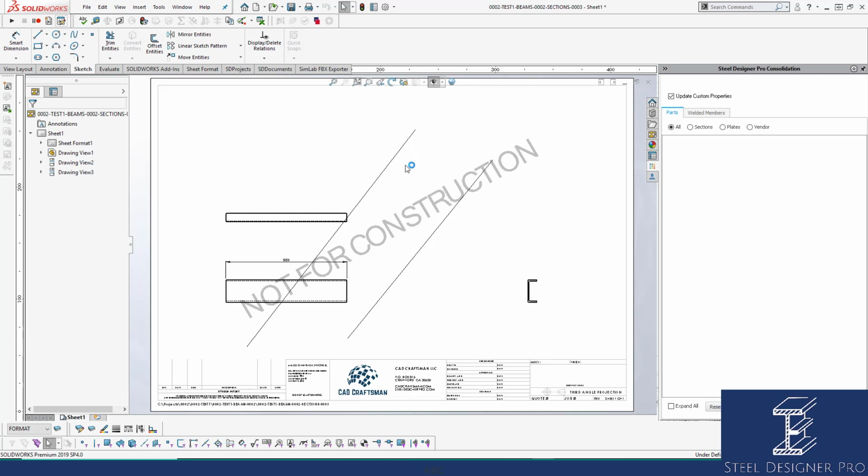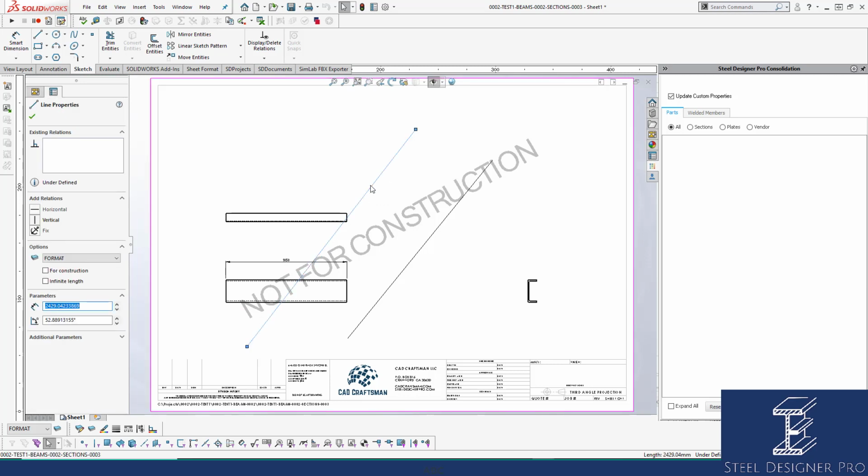So if you've got 500 components that are identical throughout the project, when you go to change a drawing, it will go through each drawing and save the current drawing into those locations and re-reference the component into the drawing. That means that realistically you're treating this like you've only got one drawing, but you may have 500 drawings. It doesn't matter which drawing you open up for which component, through consolidation it will automatically update all those drawings.